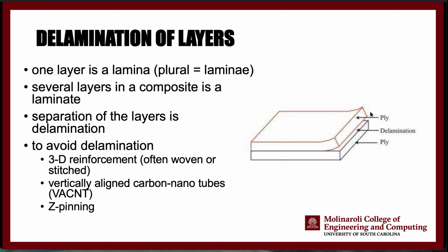So, as we are testing a composite panel, we might be able to see delamination, depending on the composite. Delamination doesn't always happen, it sometimes happens. So if you see delamination, make sure to take a picture of it and include it in your lab reports.